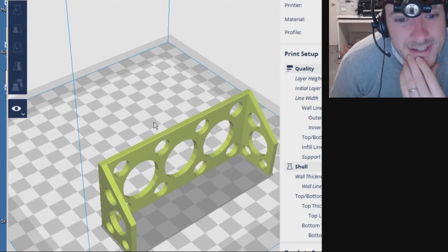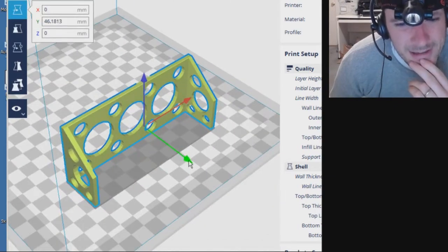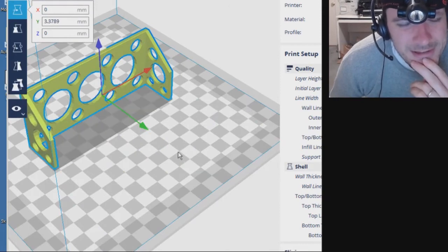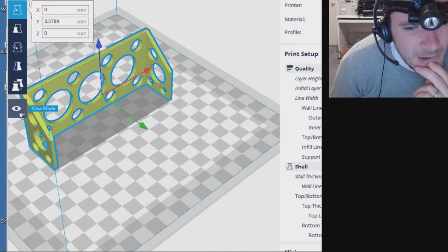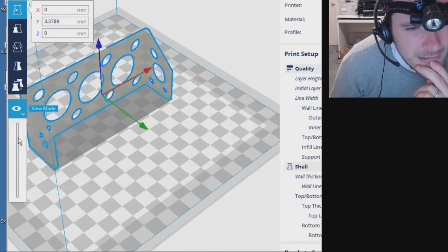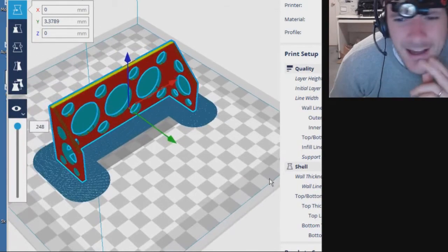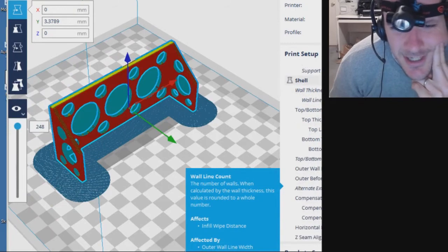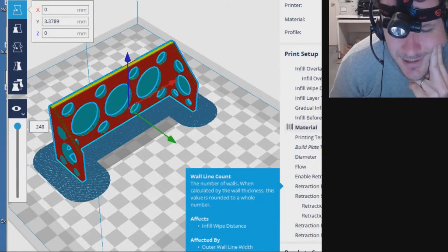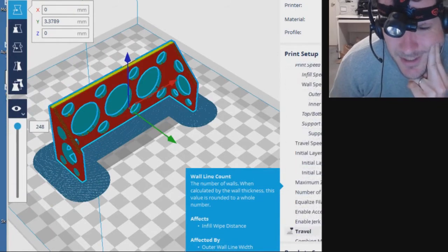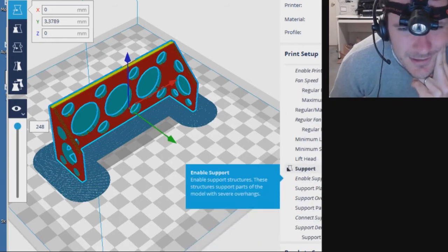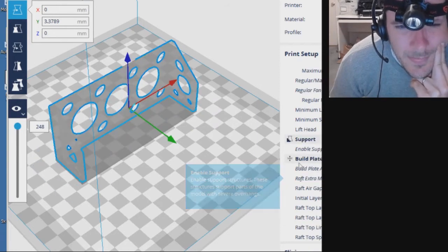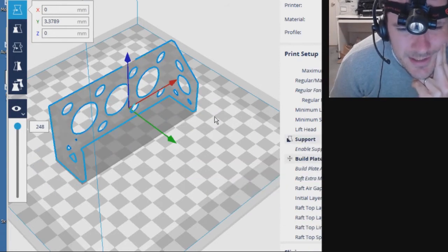It's 3 hours and 16 minutes. Okay, it's a longer print. What the heck? It takes longer to print this. Why? Why the frick would it take longer? Ah, because it supports. It's trying to support those inner circles, which we don't want. So I'm going to disable the supports. They don't need supports there. Watch this. It's going to take way less, I think.